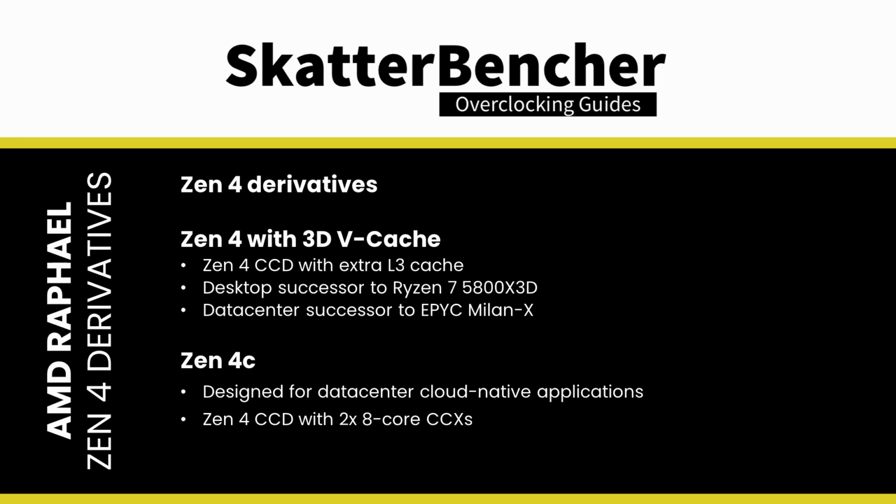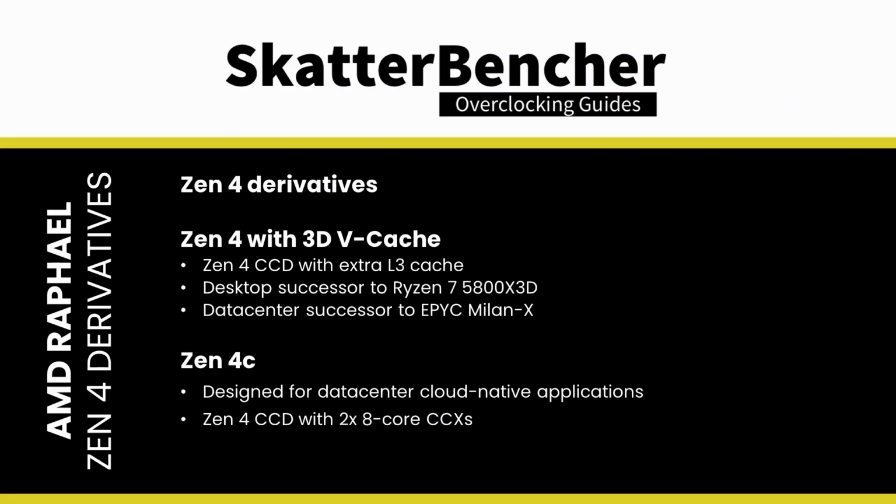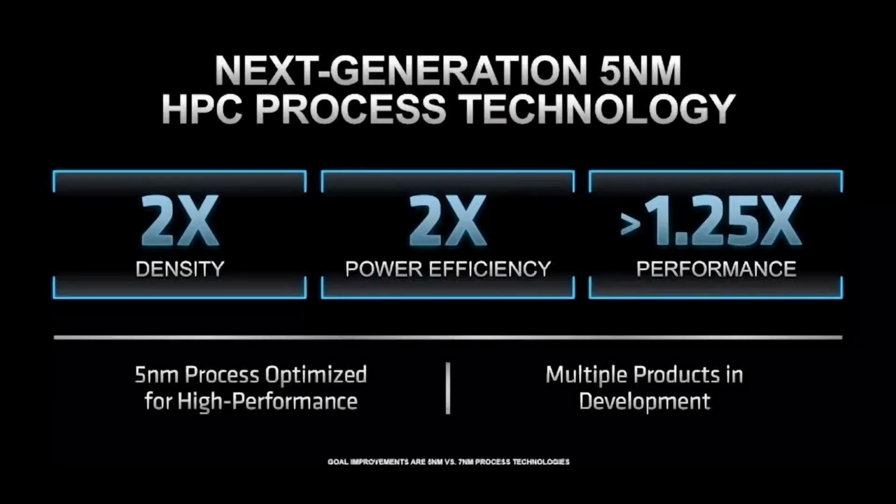The Zen 4C is a new product designed for cloud-native compute leadership in the data center. At the moment of recording, not much is known about Zen 4C other than it having ISA parity with Zen 4, but sacrificing a little bit of L3 cache for additional CPU cores. Zen 4C is expected to launch later this year as part of the Zen 4 EPYC product line. We can speculate that the Zen 4 CCD features 2 CCXs with each 8 Zen 4 cores based on AMD's 128-core EPYC Bergamo announcement. That aligns with AMD's claim that going from TSMC N7 to N5 offers 2x density improvement.